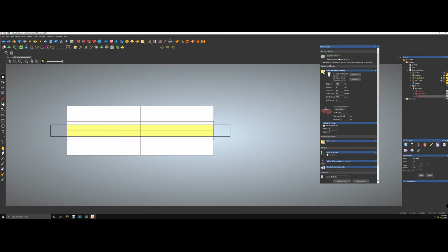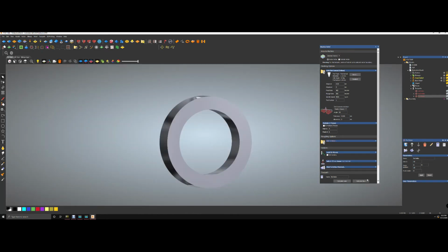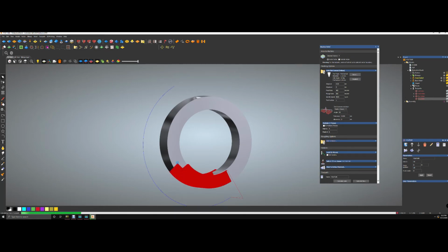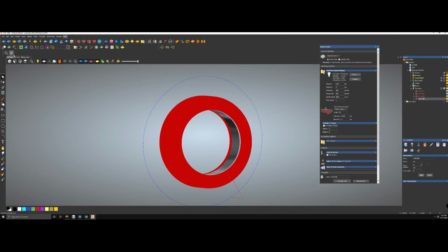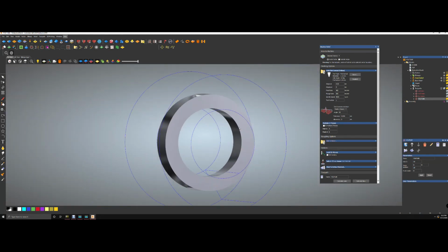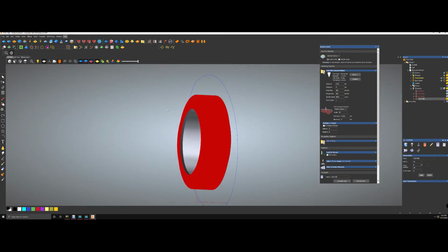So for the select vector, make sure that's selected. I'm going to show you how it works. When I say calculate now, not later, you can give it a name here. Let's call this YouTube. So I'm going to calculate now, and you're going to notice it's going to do the toolpath nice and clean. So now this is our toolpath. Now that it's created, we're going to send it to the actual mill.